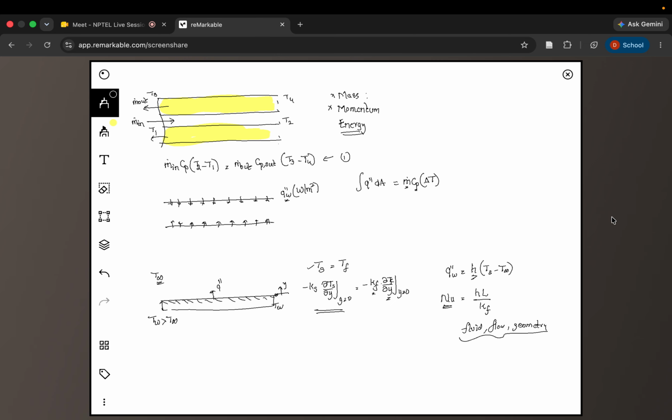All of these will be clubbed together in further non-dimensional numbers like Reynolds number, a characteristic dimension like the aspect ratio, which we will see later, or it could depend on Grashof number, or the Richardson number, like I told before. There are different numbers. We will first identify, for this particular geometry, what the non-dimensional numbers are. We will non-dimensionalize the governing equations, come up with these numbers, estimate the Nusselt number, and then find the functional relation between the Nusselt number and these non-dimensional numbers. That functional relation will keep changing depending on the problem that we'll be encountering in this series of lectures.